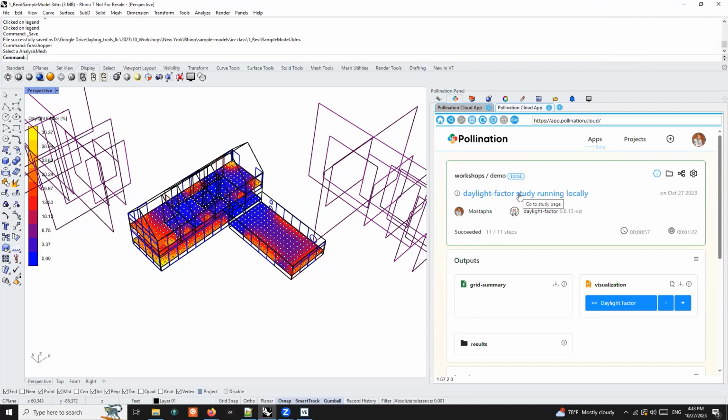And then for the LEED purpose, if I wanted to specify the regular spaces, and I wanted to just make a grid on those surfaces, do I need to just make a horizontal surface and make sensor points on those surfaces? Good question. So the first one, yes, you can totally build it face by face. You don't need rooms for typical daylight simulation. For most daylight simulation, you don't need that. For LEED, you will need them to be room-based.